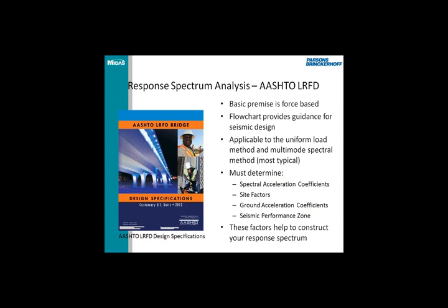Okay, so the basic premise of the current AASHTO LRFD is it's force-based, as I previously discussed. The flowchart that I showed provides you guidance for your seismic design. Using the AASHTO LRFD, you can use the uniform load method, which can basically be done by hand calculation, or a multi-mode spectral method, which is basically what you guys will be doing using your Midas model. You're combining your mode shapes to find your envelope for your forces based on your earthquake.